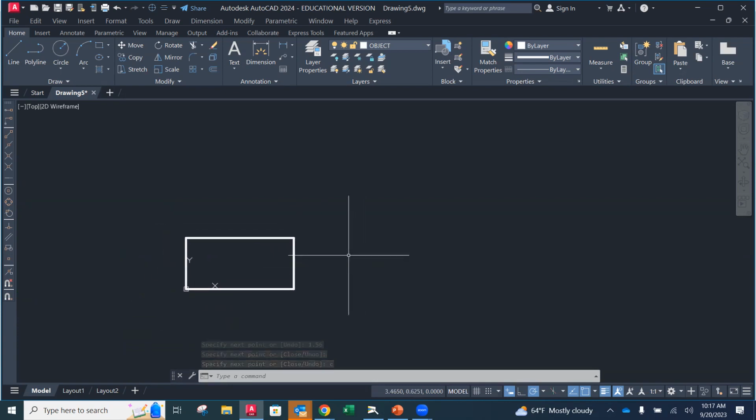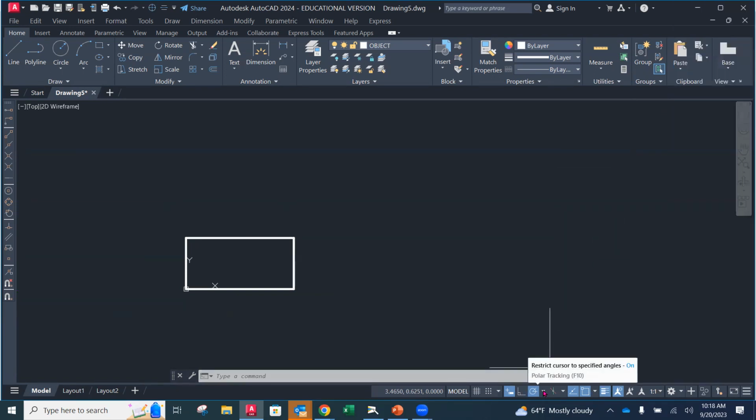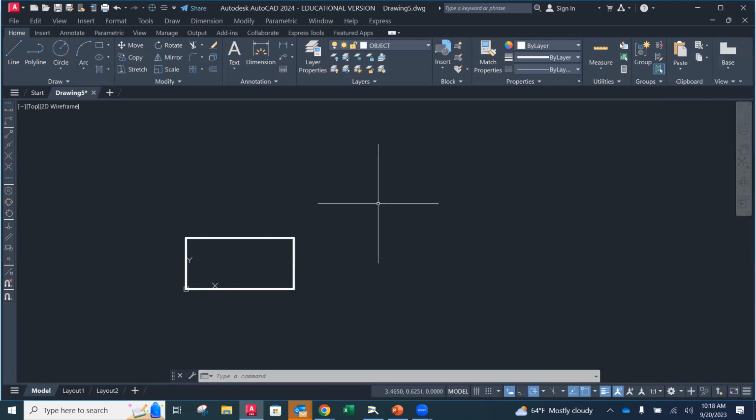Now, from that upper right-hand corner here, I'm going to create my miter line going up. Okay, so I want it to be on a 45-degree angle. I have my polar tracking set here. If you don't have polar tracking down there, you can grab it from the customize menu. I just have to find it. Polar tracking is right about there. I think it might be one of the standard settings that AutoCAD has, but you want to make sure that you have the 90, 45, 135 in there, okay? Because then it snaps to that. You can always change it if you need to.